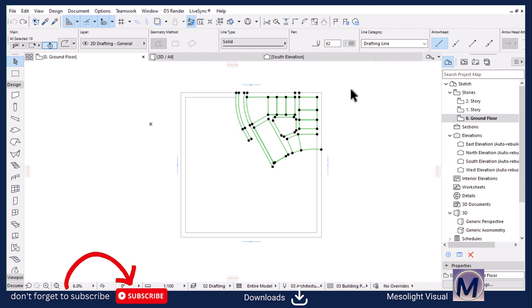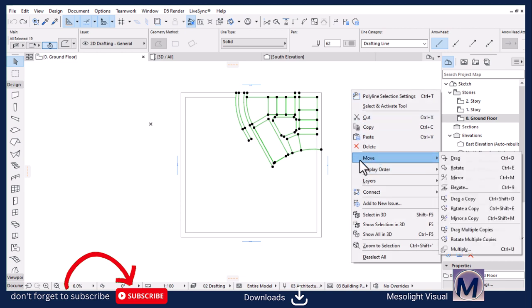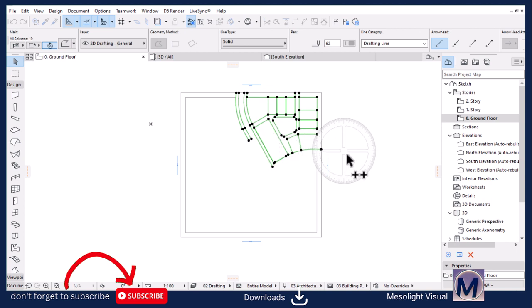So I'll right click on the space, then go to move to bring rotate multiple copies. Before you can click anywhere to rotate, you need to have guides for us to select the center of this site. So to do that, I'm going to hover the cursor by the midpoint of this line and then wait for the blue circle to appear, as you can see, and then do the same to the other side and wait for the blue circle to appear, and then that's when it gives you the center of the whole thing like that, and you can click.